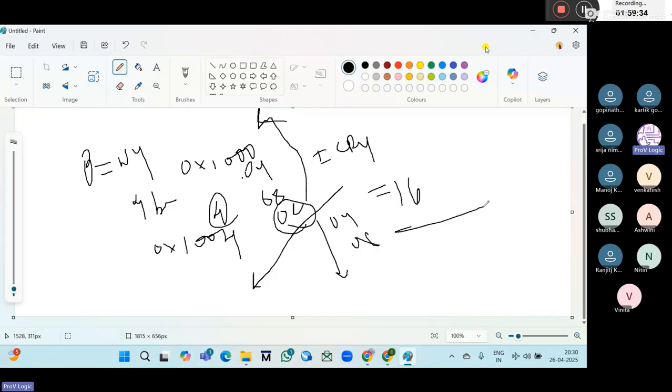So starting from the aligned address. What is the aligned starting address? 1004. Okay. So it aligns the start address to the boundary. The lower 4 bits of the address are ignored for the wrapping. So now here 1004 and 1008, 100C, and again 1000. It wraps around here. After 0C, the next address will be 1000. So it will wrap within 1000 to 100F, like that. It's a fixed size.